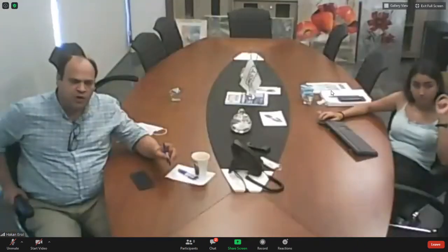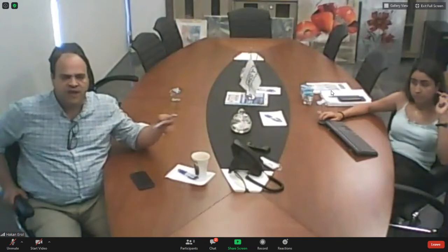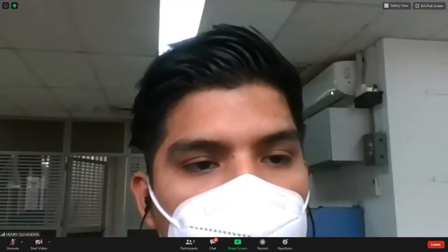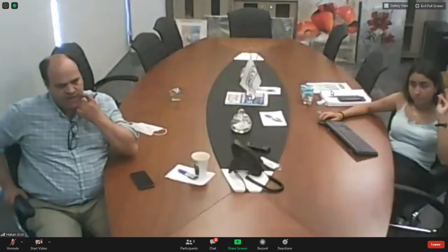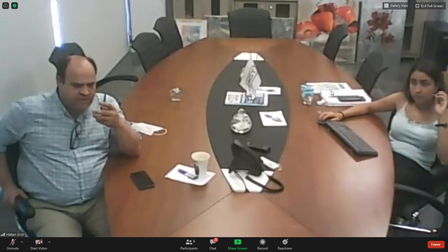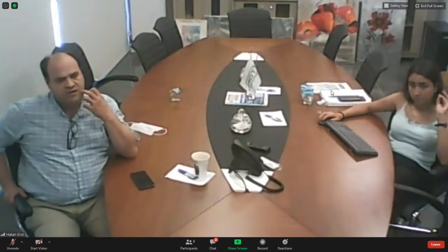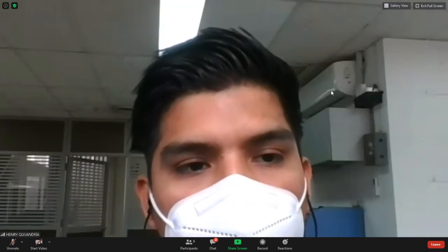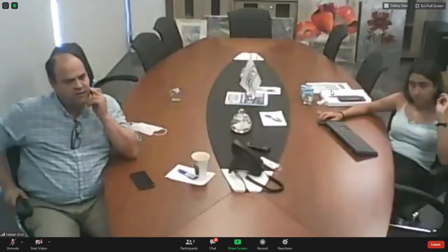Yeah, that means your question was correct. So that means you can use F7, F8, F9 medium type of filters, not G4 pre-filter. Yeah, I heard this question also from other customers. So you are correct. They can use them in shopping malls or in airports.